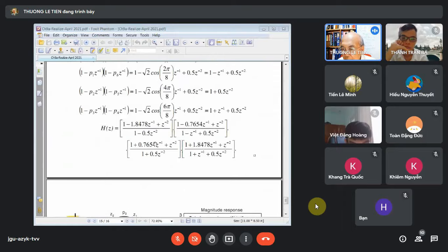You may ask why we have to split them up into second order sections. It is quite convenient when you design a digital filter, particularly when you write a program. Every time, you can put the second order section as a subroutine by changing the filter coefficients, and call it to build a high order digital filter. For example, for a fifth order system, you can call the second order section 2 times and the first order section 1 time, and put them in cascade.